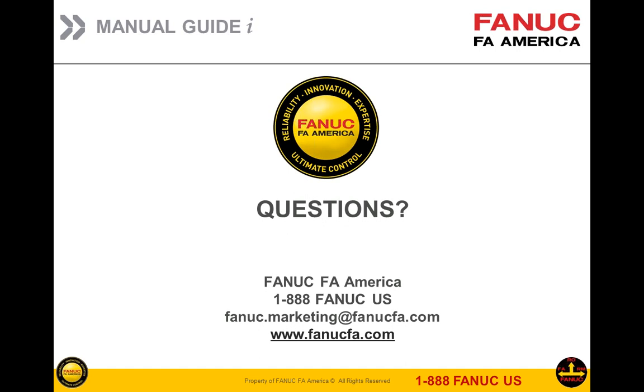Okay, that sounds good. How about, can I do a mirror image? Yes, you can. There are several different ways of doing it. Recently I did it for a customer where we put it in a fixed form. G51.1 turns it on, G50.1 turns it off, and then you tell it which axes to mirror around. Also, when you go in and draw a free-form shape, there's a mirror image option there that does the same thing. So if you did a pocket on one side, then you wanted to mirror it on the other side, you could do that. It's very easy.